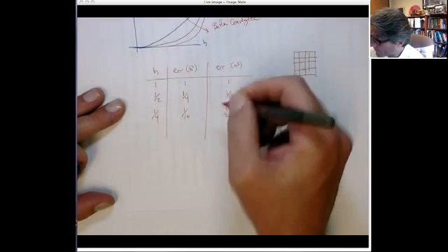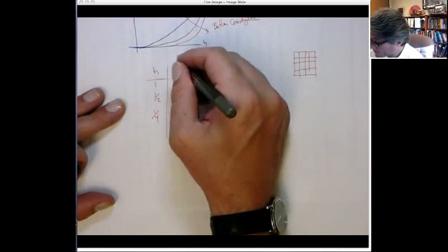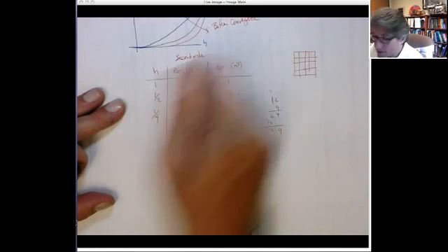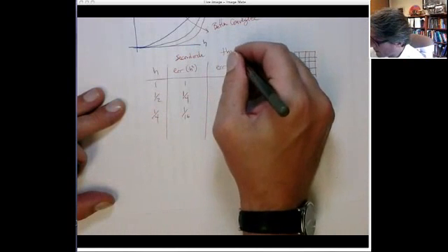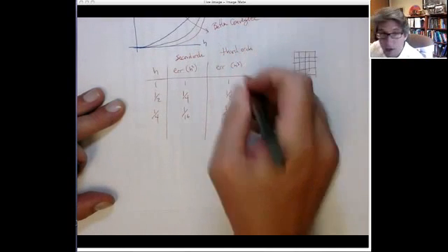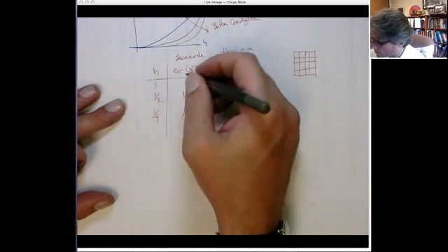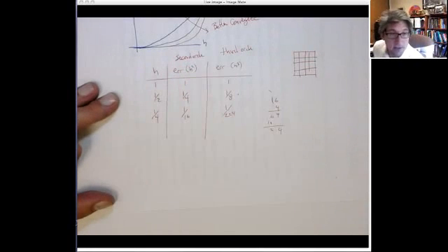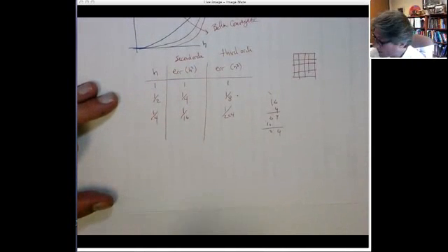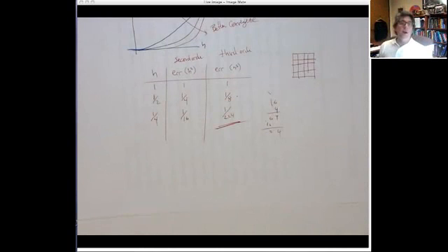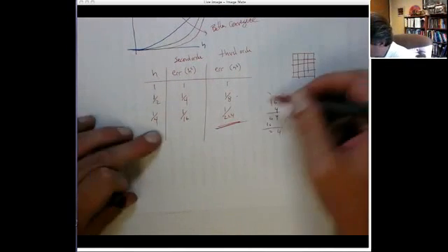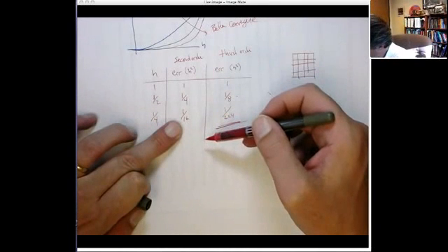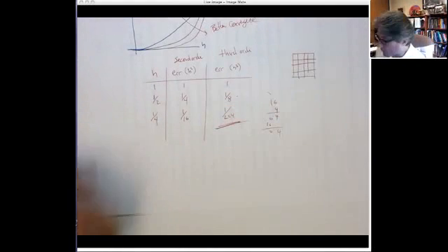So this type of convergence we call second order convergence. This would have third order convergence. You could have fourth order, or likewise you could even have first order convergence where the error goes directly as h. So if you had first order, your error would go just as h does. You halve the element size, your error drops in half. So if you can get higher order convergence, your errors drop off very quickly, okay? So even if you compare similar amounts of degrees of freedom, you just tend to get better performance, okay?